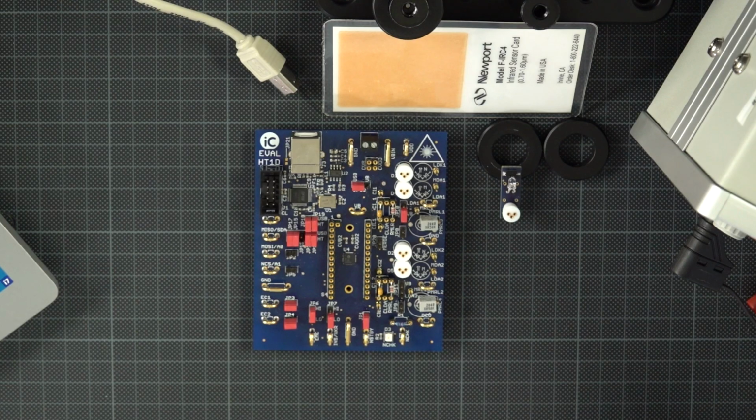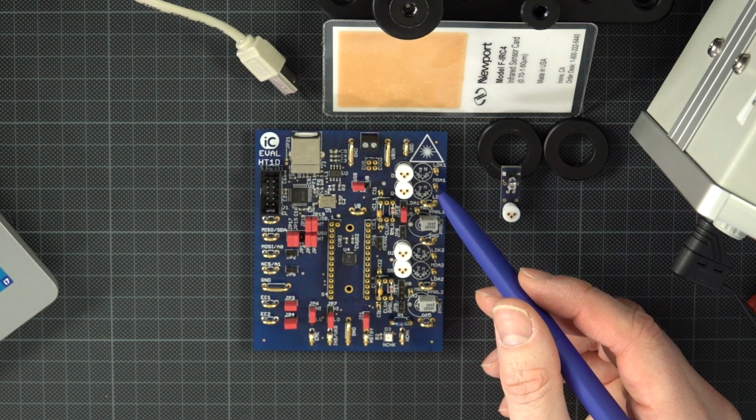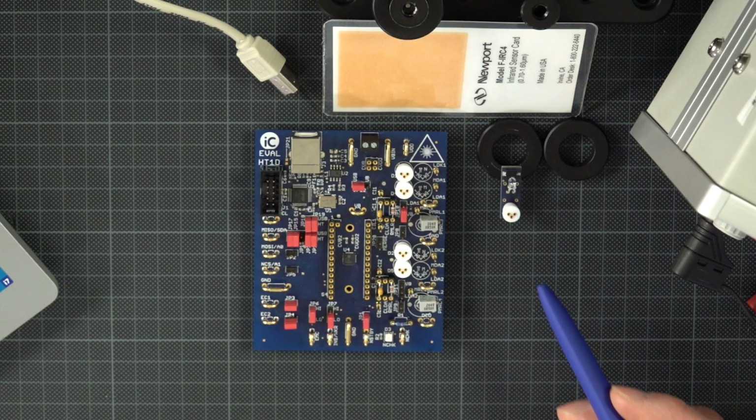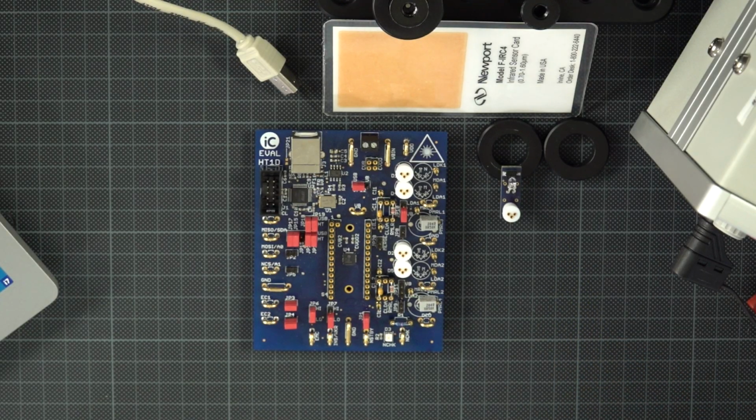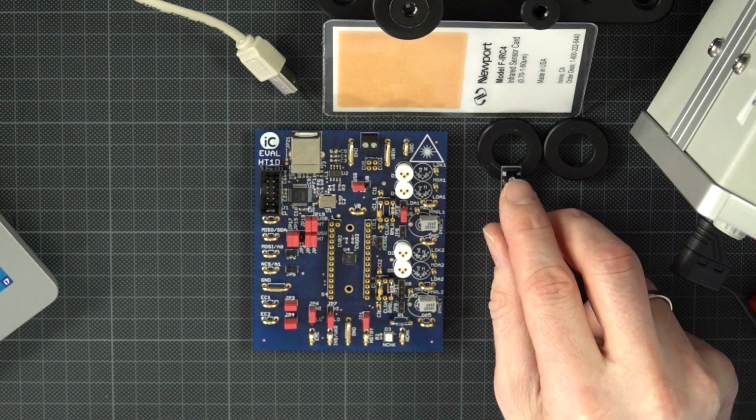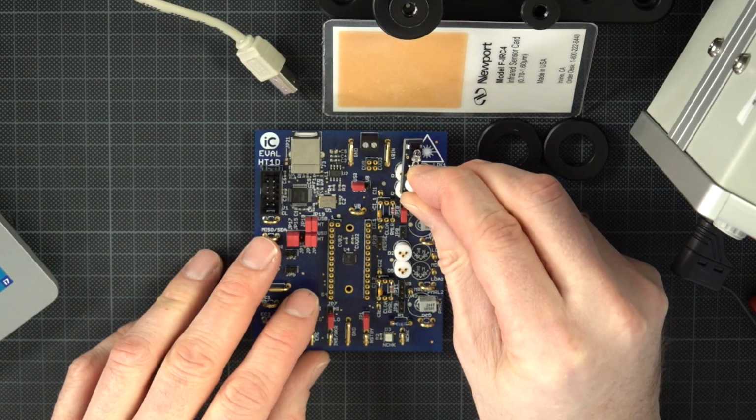If your laser diode housing has only 2 leads, which indicates that there is no monitor diode, you can still operate it without feedback and a constant current in automatic current control mode. You can infer from the little drawings on the PCB or the numbering in the circuit description in which orientation to inlet those in the socket. The laser dummy that is included in the evaluation kit is an N-type, and this goes into the other socket, which is D1 for channel 1.